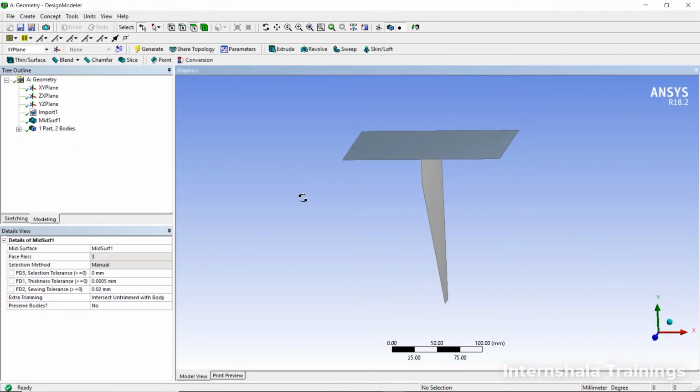See, now what happened: we have turned the solid body into a 2D object. The main advantage is, if we are able to convert such simple geometries which have a lot of plane faces into these surfaces or 2D objects, the computation time as well as the computational resource requirements and computational cost will all be reduced, and the project can be delivered in advance.